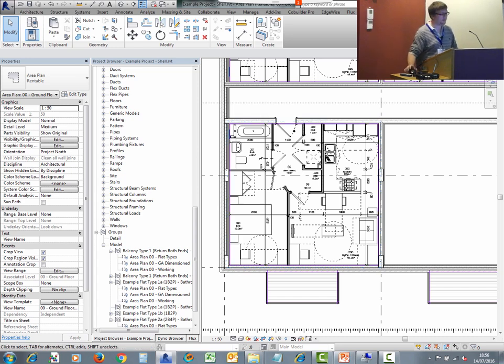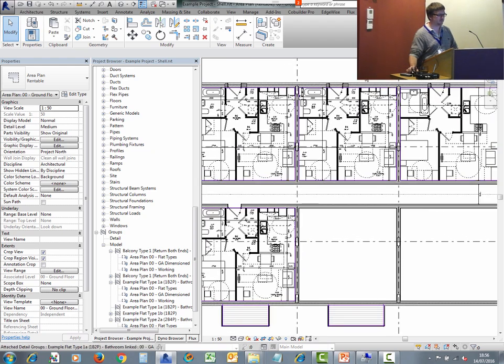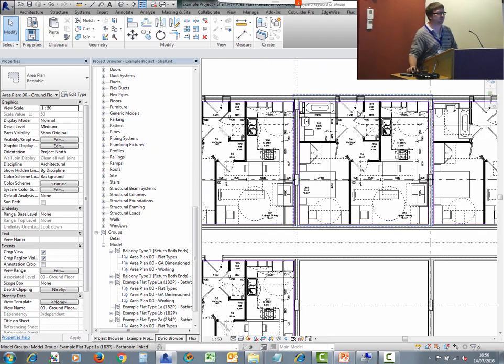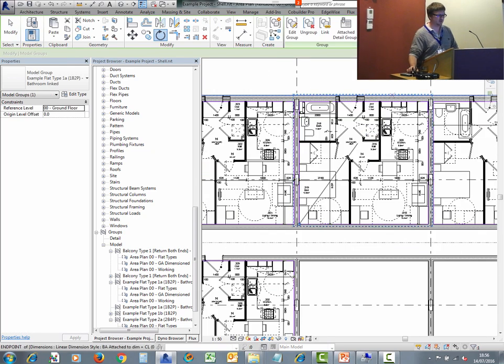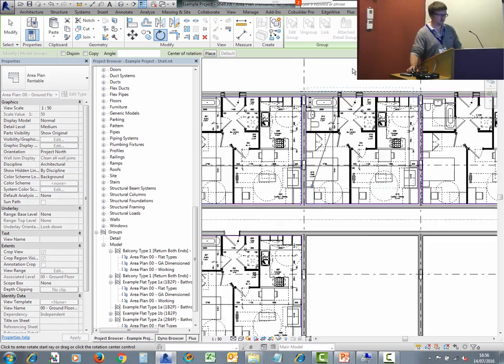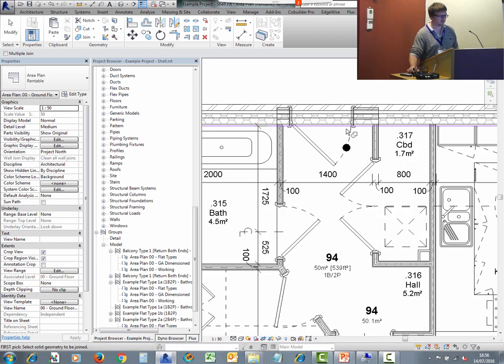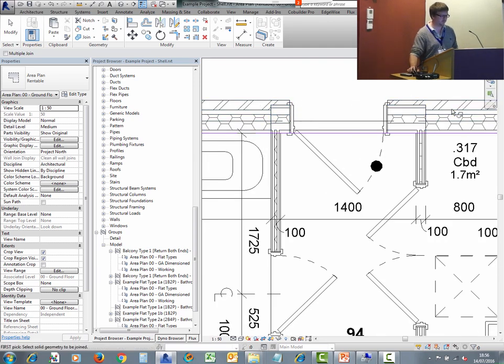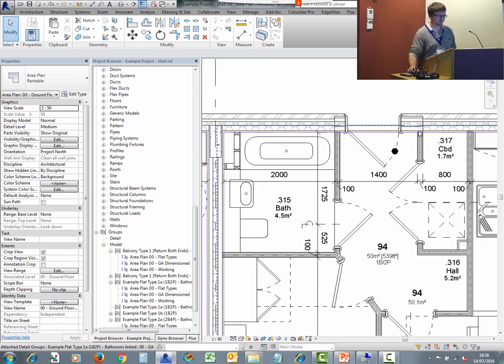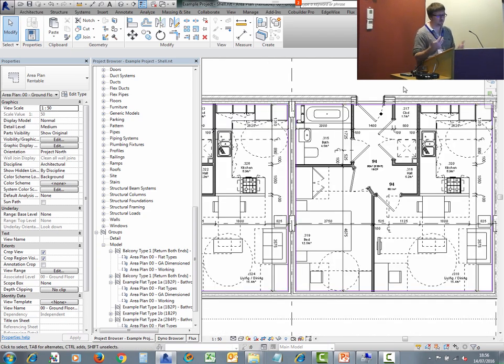Is it on in that instance, or when you've joined the wall with the door? It hasn't. No, so it hasn't. I mean, obviously these are the wrong way around anyway. You'd go around and do that in each instance, and that's going to play funny things there because the walls are different thickness. But say that's the benefit of model groups, that they'll interact in that way.